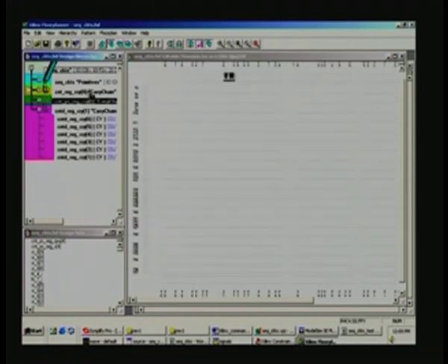In the editable floor plan we have seen that this is the layout of your chosen FPGA, say 100,000 gates equivalent, and you can see all the pins marked here on all these sides, for example pin 3 here, 4, 5 and so on. It is numbered like this, in increasing order in anti-clockwise direction, and I wonder whether you can see some faint lines here. They are all basically squares, and in each square there will be a group of primitive cells, for example MUX, LUTs and all the primitive cells which we have already seen.